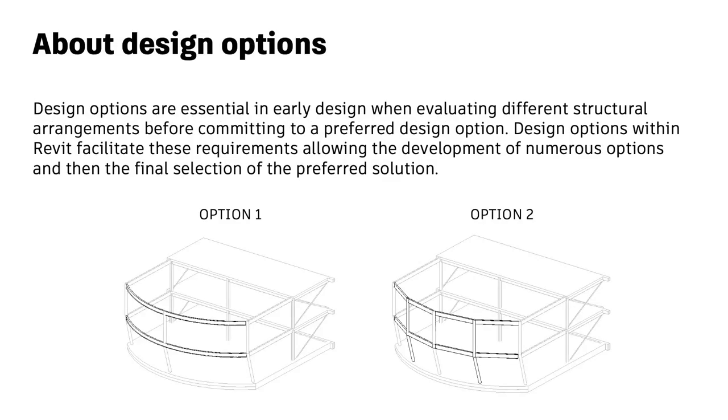Design options are essential in early design when evaluating different structural arrangements prior to committing to a preferred design option. Design options within Revit facilitate these requirements, allowing the development of numerous options and then the final selection of the preferred solution.